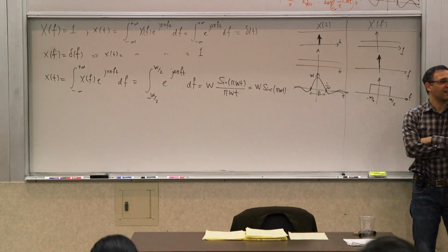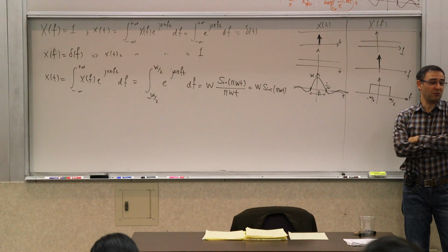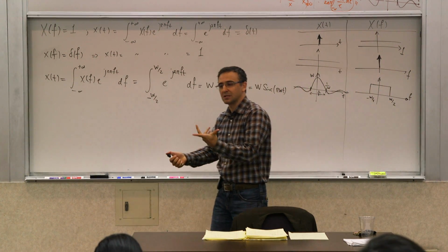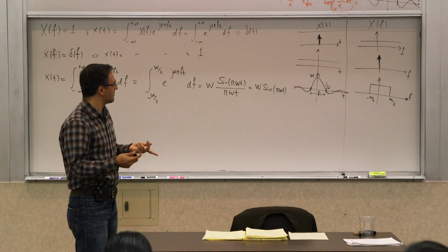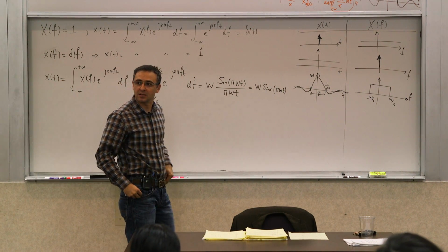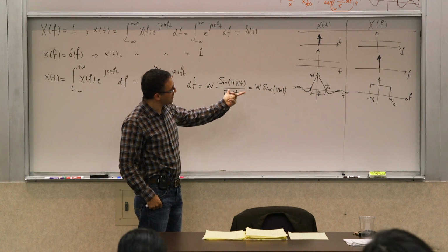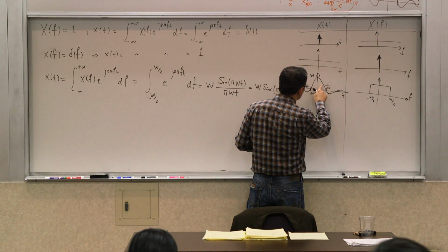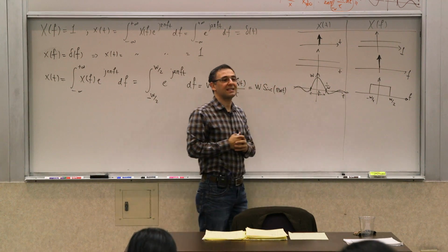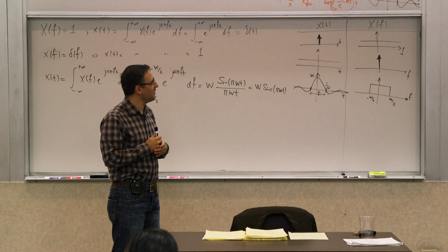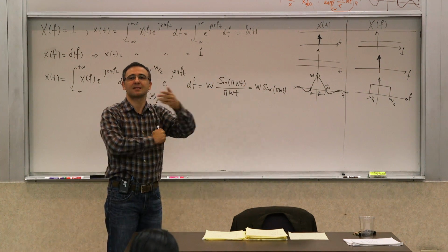So it violates causality. You can actually create non-causal systems in signal processing, but it means that you're doing something that's not physical, though you can do mathematical things that work. You can make that, but the problem is causality. And this is symmetrical. My drawing is kind of bad. So does it mean that it's hopeless to make a filter that has maybe not exactly that, but something very similar to that?